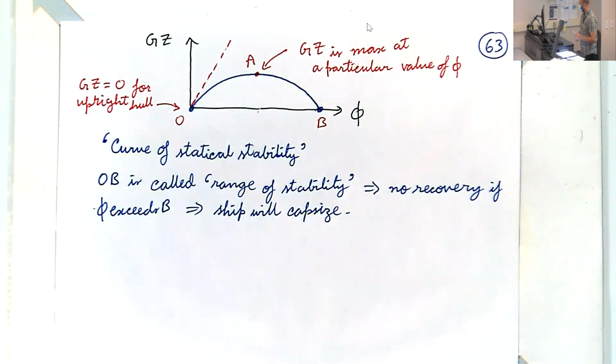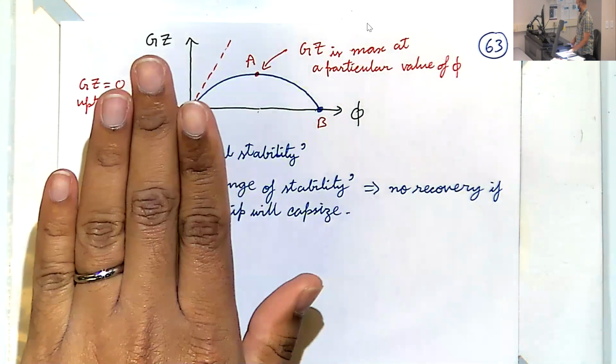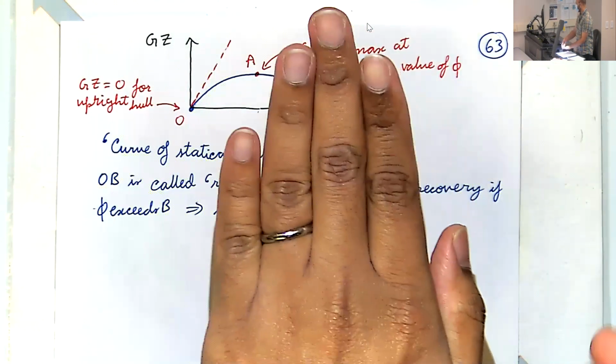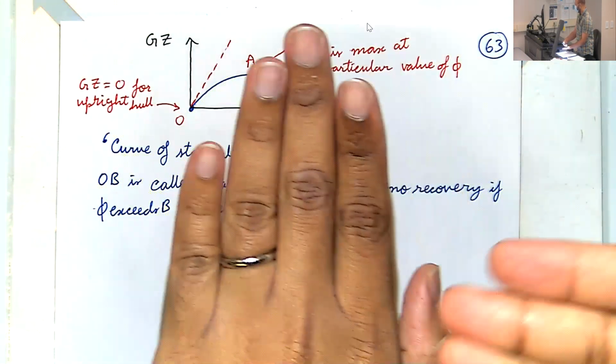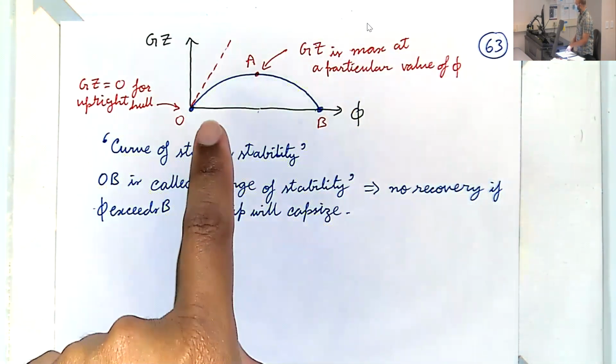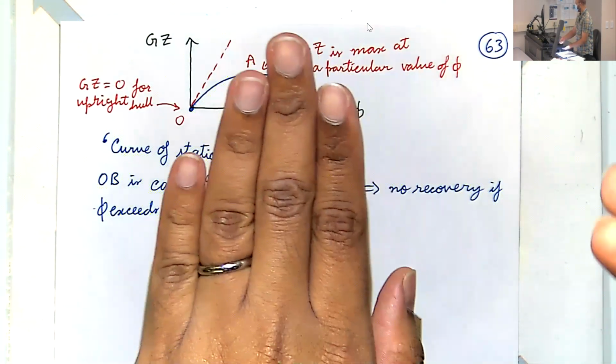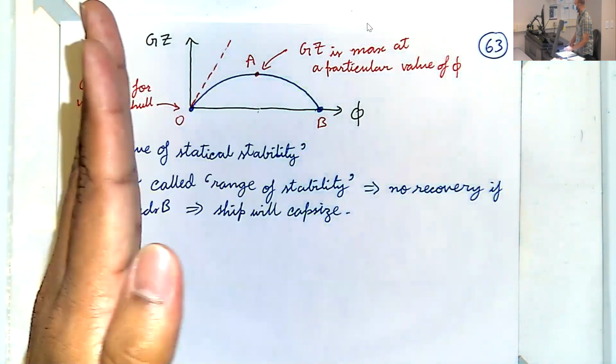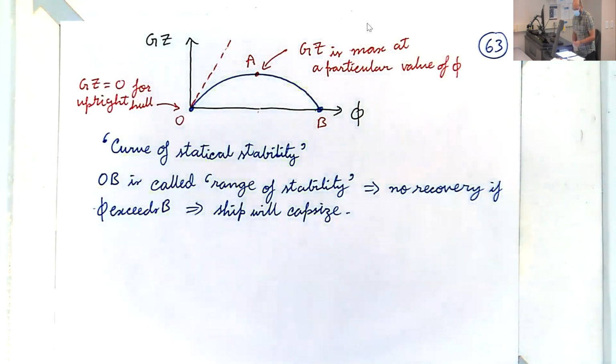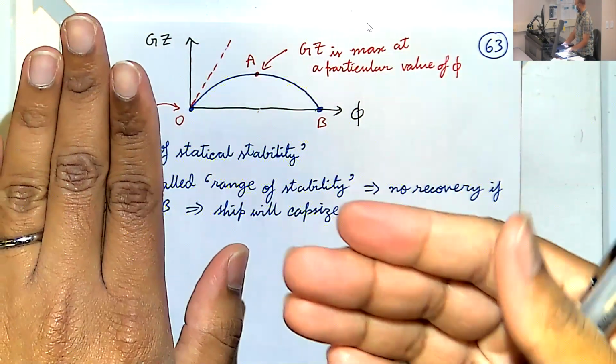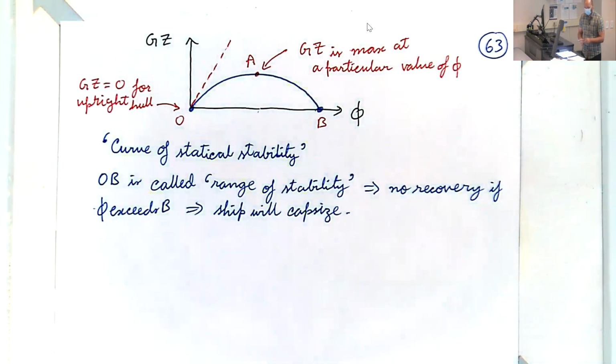All right, then there's one more important thing this graph tells us. Think about you have your hull and there's waves hitting your hull from the side, or there's a strong wind from the side. This graph can be used to determine what is the maximum torque generated by this wind, sideways wind, that your hull can tolerate. Can you think about where that point might be? So the graph is telling us how much maximum wind could we potentially tolerate.